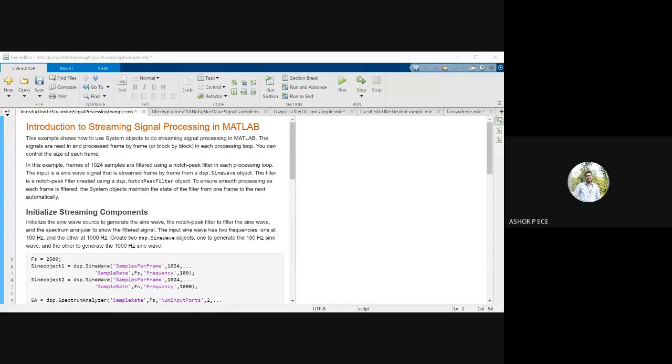Whenever you want to see the frequency domain visualization of any signal, you will buy a device called a spectrum analyzer. A spectrum analyzer is very costly compared to your CROs or CRTs or DSO, digital storage oscilloscope, because you are converting the same signal into the frequency domain. Essentially, you take the Fourier transform of the signal and see it in the spectrum analyzer.